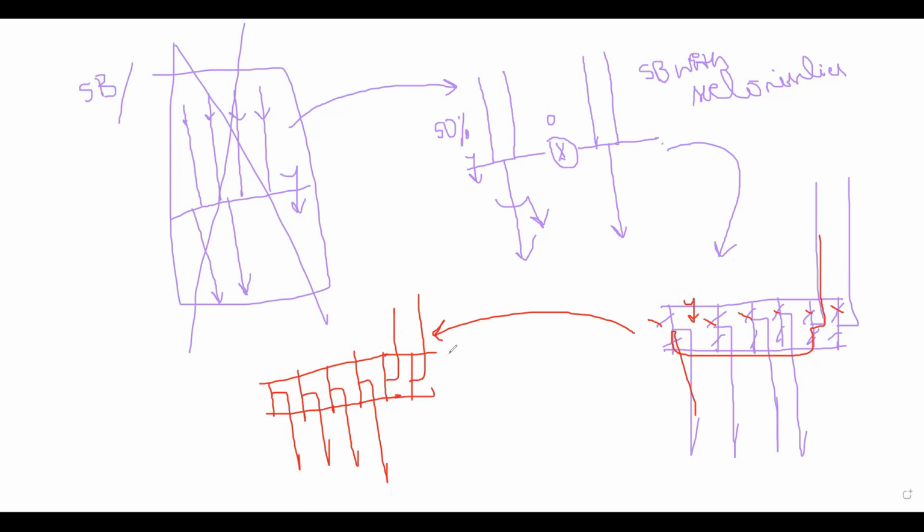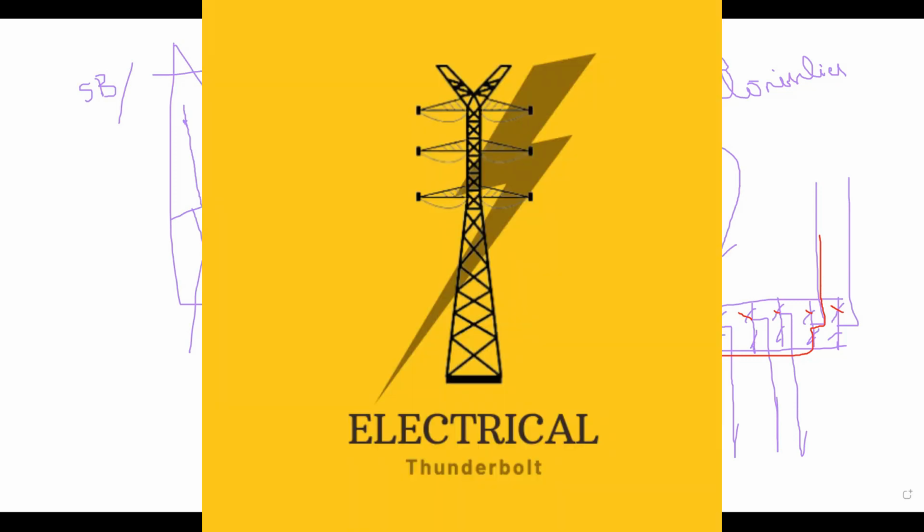And to avoid that interruption, we have a scheme called double bus with the bus coupler scheme. This is the bus coupler. In this scheme, suppose I want to take this bus into maintenance. Generally, two buses are in the live position. Now I can open up this one.